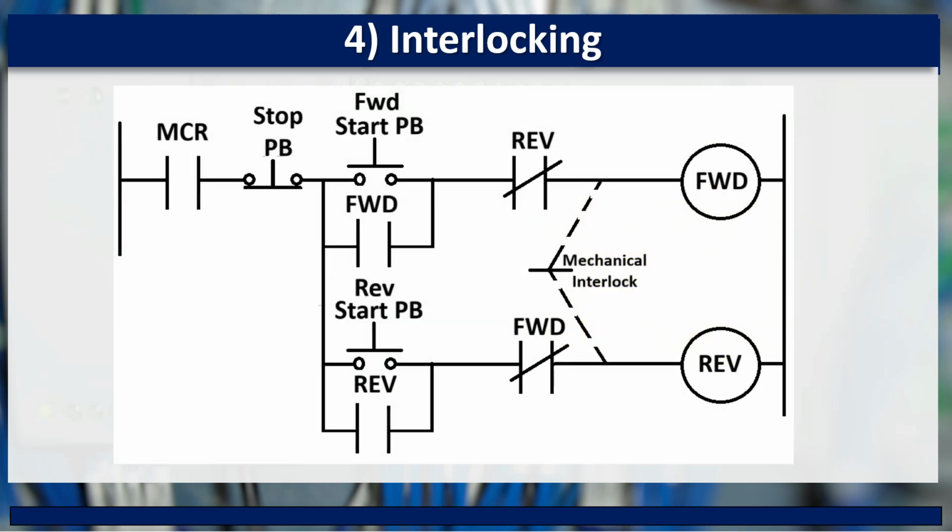If the control circuit is not designed correctly, pressing the forward and reverse push buttons at the same time can command both contactors to energize. Because contactors and auxiliary contacts do not operate at exactly the same speed, one may pull in first, or the control circuit may chatter or behave unpredictably. That is precisely why both electrical and mechanical interlocking are required. Without them, the result could be very bad.